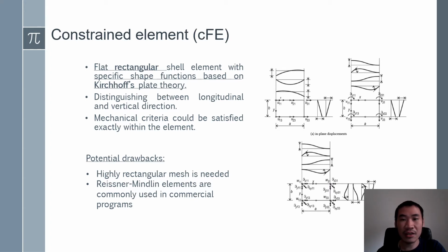This special set of shape functions allows the mechanical criteria for modal decomposition to be exactly satisfied within each individual element. However, it also causes some potential drawbacks, as a highly rectangular mesh is needed and the comparison to the Reissner-Mindlin elements, which are commonly used in commercial software, is difficult.